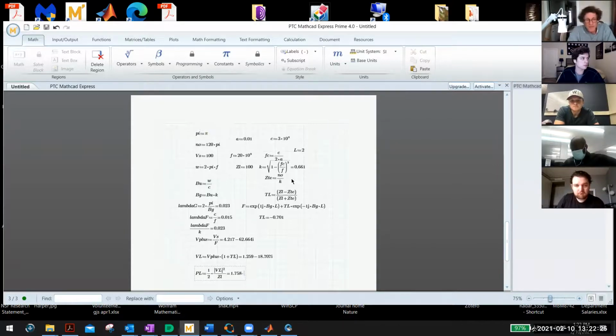Now, there's something I didn't tell you. Whenever you feed a waveguide, in order to get perfect coupling from the source that I assumed, you have to impedance match it. And even then you don't get perfect coupling, do you? The most you can get if you impedance match something is half the actual power, right? Or half the voltage. Do you all remember that? The maximum power possible, and this is true with waveguides, there is no such thing as having a source without a characteristic impedance. I omitted it because I'm just saying this, what do I call it?